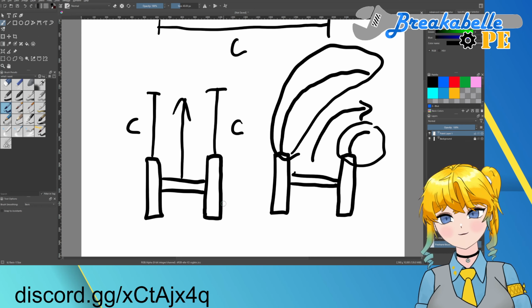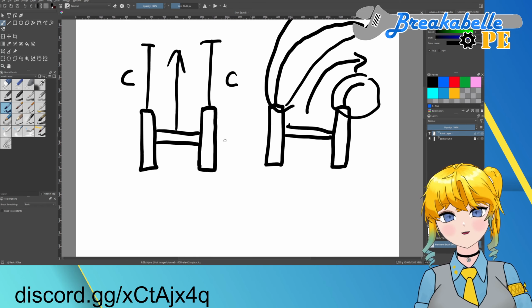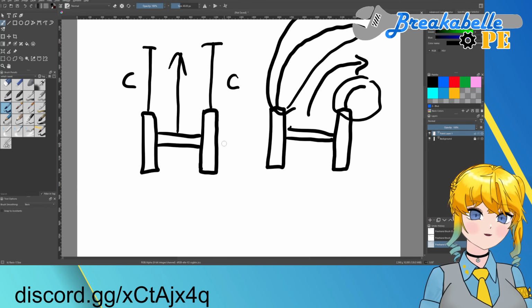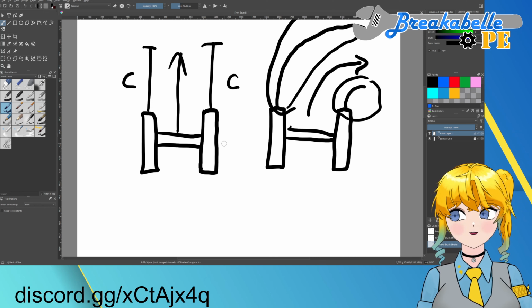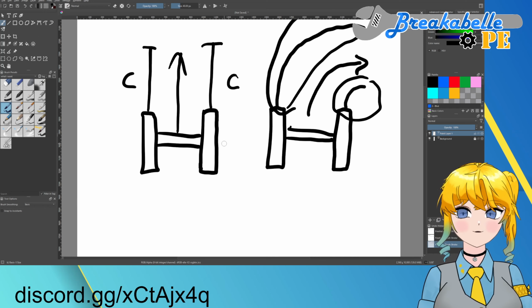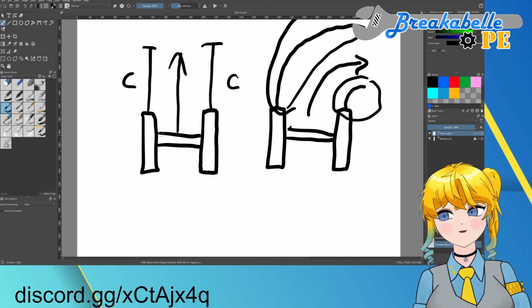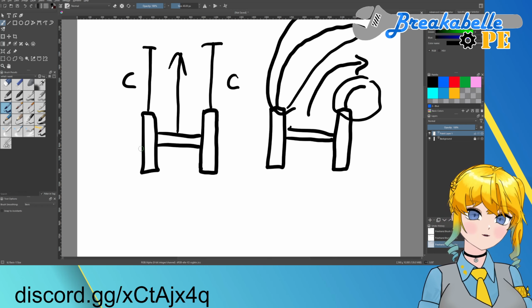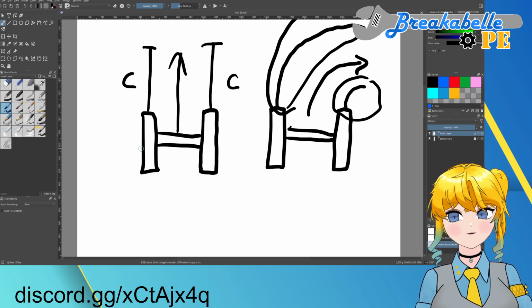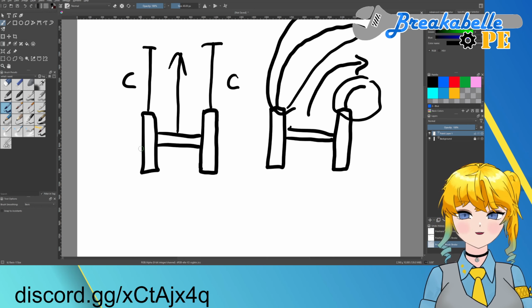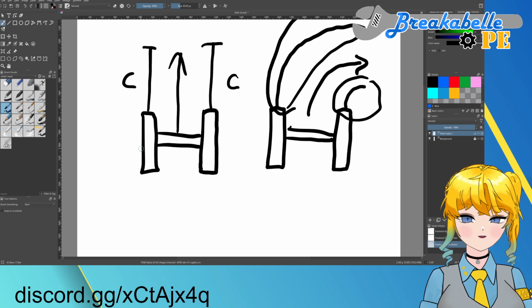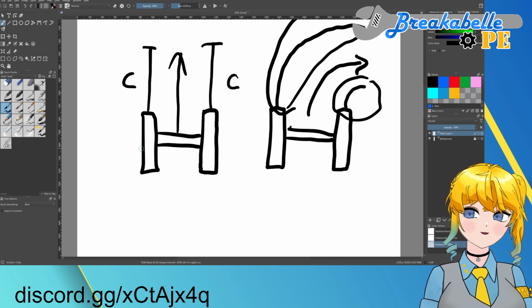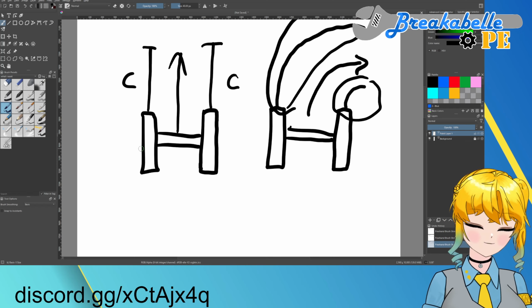So we have established that with this situation where we have two wheels linked like this, they can only roll straight. The only way that it would ever turn is if one of them is slipping. Of course, when you're driving your car, you don't want your tires slipping. So cars, we definitely all want to avoid any situation of slipping. Slipping is bad, does a tremendous amount of damage to your tires, and it can do a lot of damage to your drivetrain too.